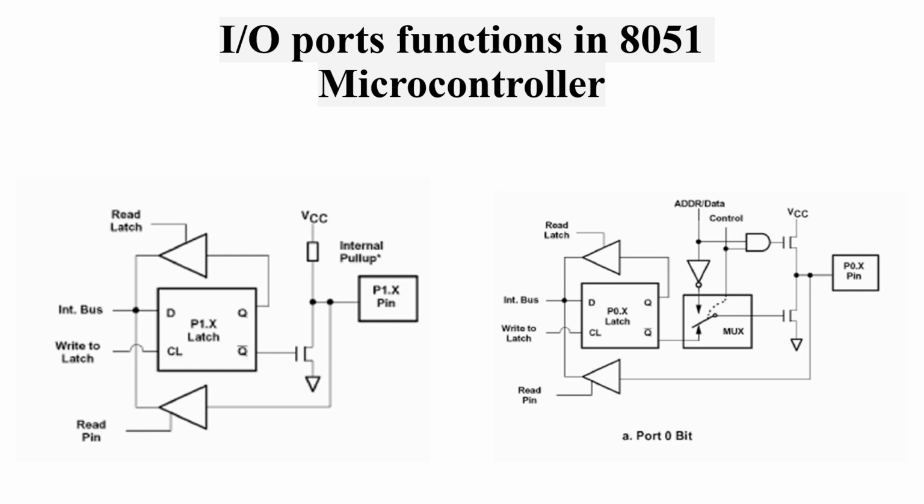Here you can see what I told you. It is going to have the lower address buses. So control, lower address bus and data with the control it is having. You have a latch across it, and also you have a mux function across your port 0.